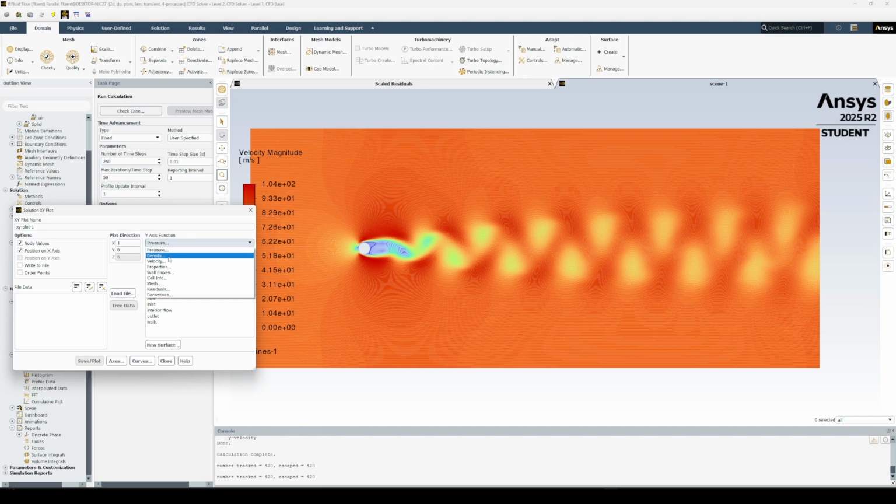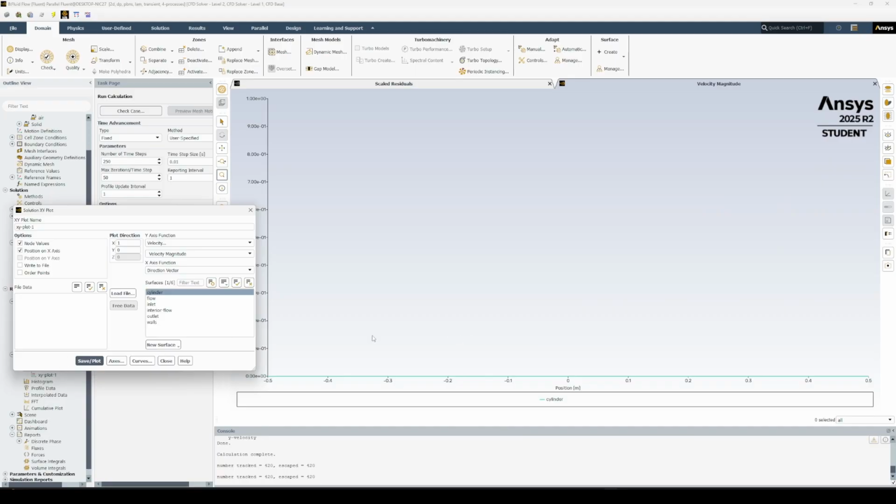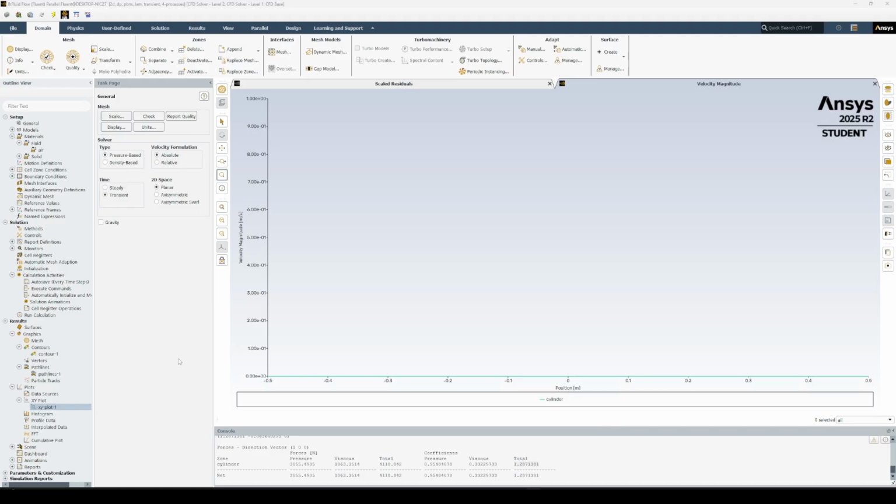So now we're going to go to the velocity distribution, select cylinder. Here we would write to file, again, put in your Excel, create your own graph, write, save, and display, and so the velocity distribution over the surface of the cylinder is going to be 0 because it's a no slip boundary condition. So the velocity on the walls will be 0 everywhere on the surface because this is a laminar with vortex shedding.